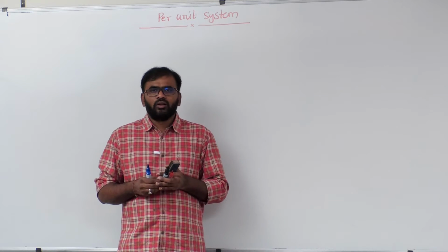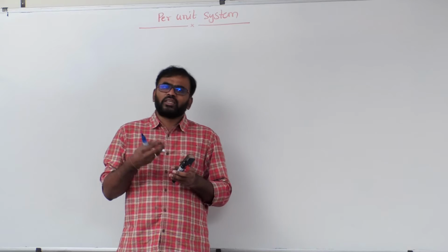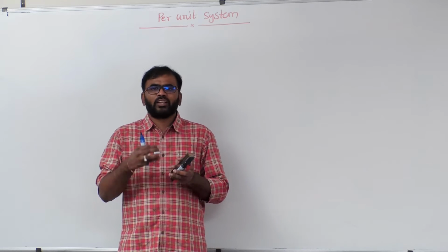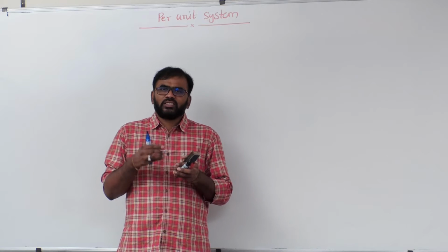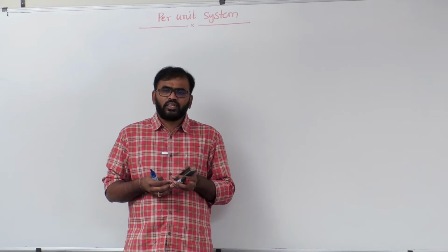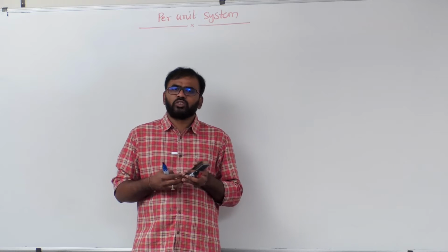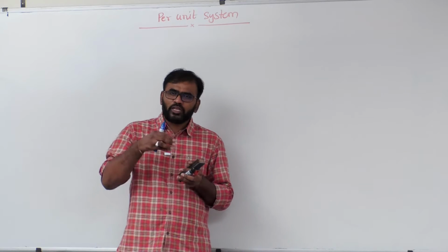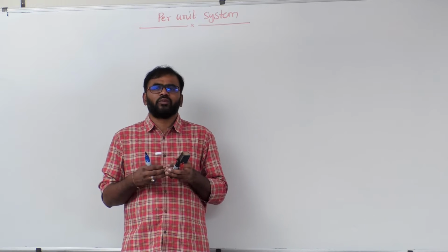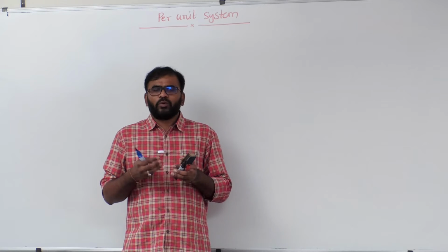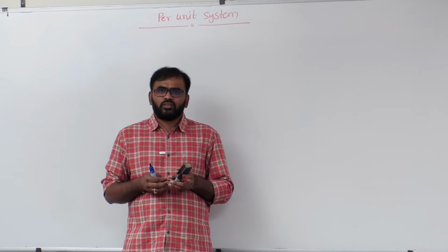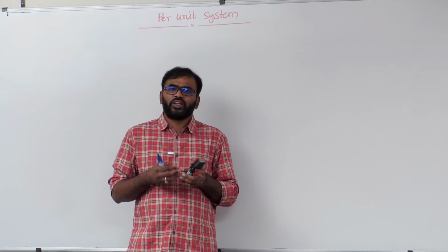We took an example by which we drew the impedance diagram in per unit form and in absolute form. And later we concluded that the impedance diagram in absolute form is really a complex one. The reason is, when you are doing the analysis using the impedance diagram in absolute form, there is a discontinuity in KVL equations. So that's why analysis becomes very complex. But when it comes to the per unit form, there is no discontinuity in KVL equations. So that's why analysis becomes very simple.